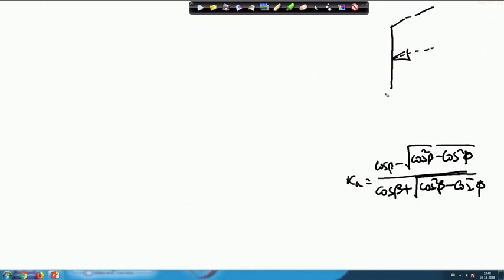So, something like this. I can imagine the pressure will be acting like this, triangular from here, and this is the pressure diagram. At this point the pressure will be equal to 5 multiplied by gamma and Ka. If I put the values of beta equal to 15 degrees and phi equal to 32 degrees in this expression, then finally I will get Ka equal to 0.34.